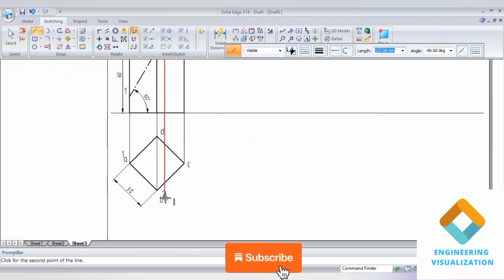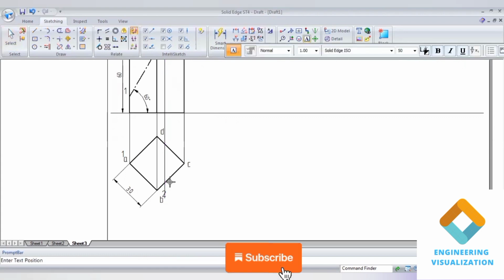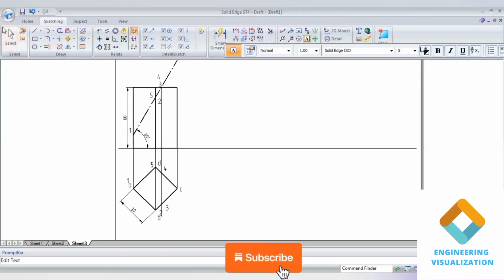Somewhere in between. That's why I'll be drawing a projection line from the intersection of these two points. By projecting it, you can see this is not falling on B, it is falling in between B and C. So that's why we have to draw another line here. I'll make that line a continuous line. So we can give that as 3. Point number 4 is not falling on D, it is falling in between C and D. Then point 5 is falling exactly on the vertical edge D. Now we are done with the namings.